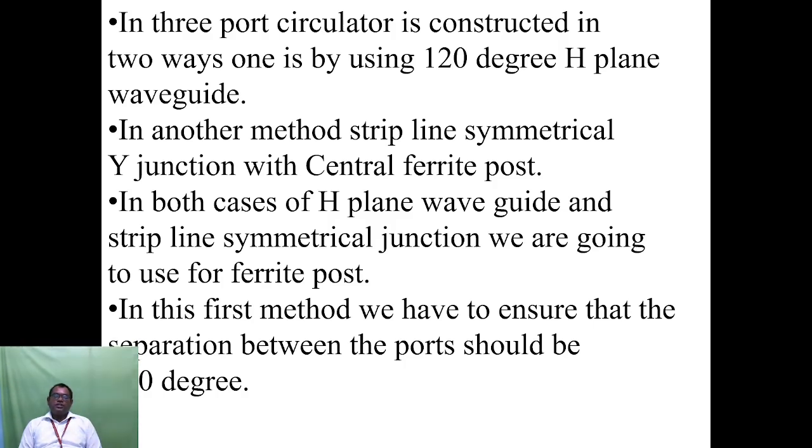In the first method, we have to ensure that the separation between the ports is 120 degrees. As I told you earlier, port 1 and port 2 should have a 120-degree phase shift, similarly port 2 and port 3, and port 3 and port 1, 120-degree separation.